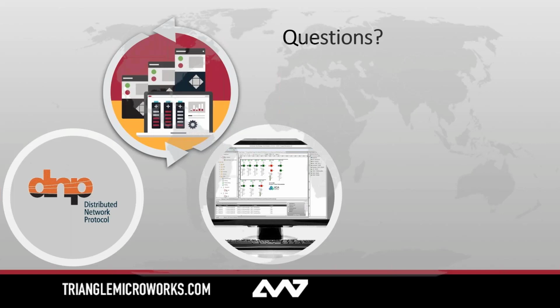So let me answer the second part, because that's the easiest part to do first. Yes, if you bring in a 61850 server and it has multiple report control blocks, GOOSE messages, any of this type of stuff, once you have all the adapters configured and the device simulated, it's going to behave like you would expect it to if it was in physical hardware. That means sending GOOSE messages out whenever those values change, and receiving controls and commands and responding properly to those.